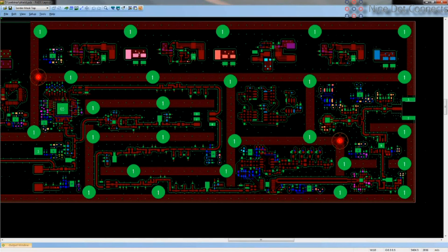You can see along the top here that I've got a group of power supplies. These are switching power supplies that are extremely noisy. In no way do you ever want to put these circuits adjacent to your RF circuit. So placement is key there, and this just happens to be a good depiction of shielding. The area that you see here is copper that's going to come into contact with the enclosure, both on the top and bottom of the board.